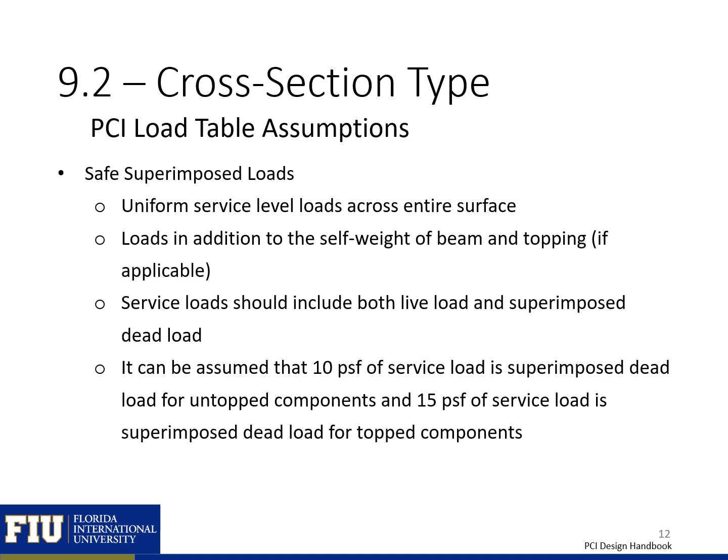On the next couple slides, I'm giving you just a quick overview of some of the assumptions that went into these load tables. Again, the load tables generally should just be used as a preliminary design aid, and you should, at the end, after you've selected your cross section and selected the number of strands, your strand size, and the location of your strands, go back and analyze your actual section. But anyway, so some of the assumptions that went in.